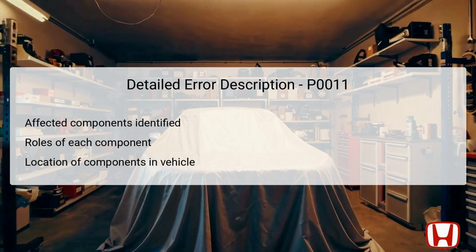Located typically on the engine cylinder head, the solenoid is easily accessible during inspections. Meanwhile, the VTC Actuator A is responsible for adjusting the position of the intake camshaft based on the oil pressure it receives from the solenoid. The actuator is often found mounted to the front of the engine, directly driven by the timing chain or belt.